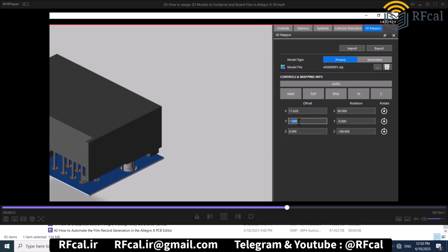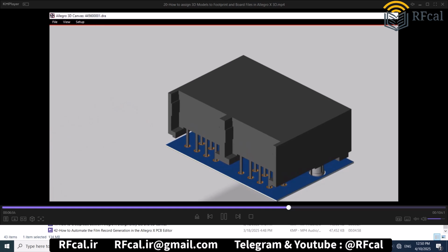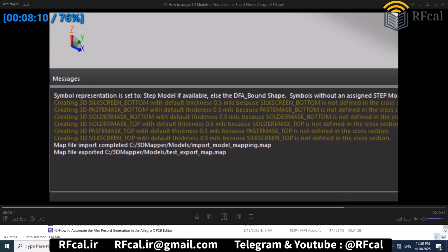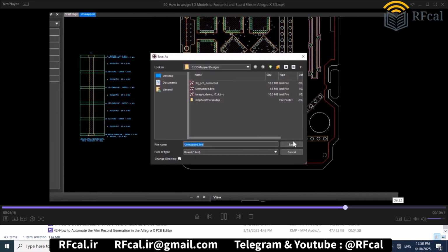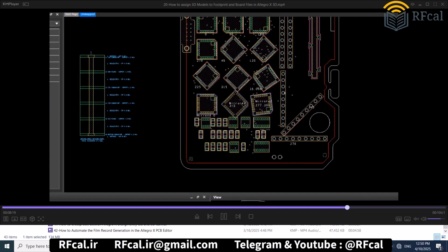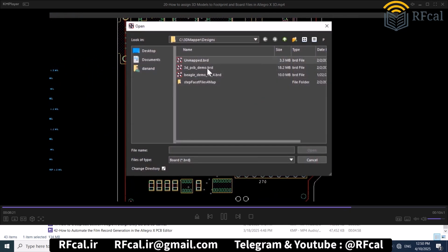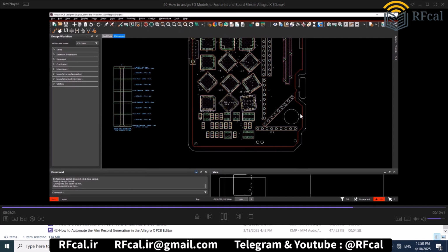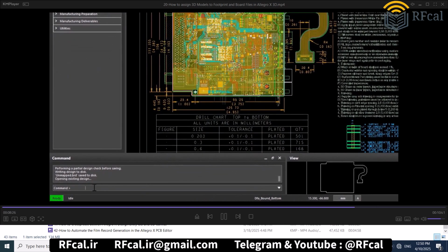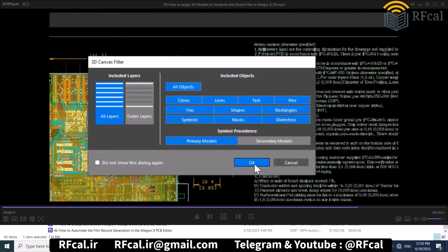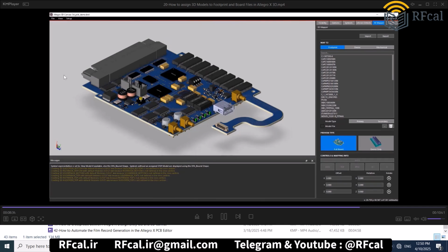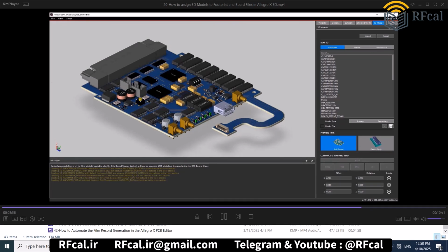position and its orientation. I am going to show you an example of importing the 3D mapper files. We have already set our library paths where the 3D model is. We will check how we will import the mechanical 3D model in the board file. Open the board file named 3D_PCB_demo.brd and open its 3D canvas. Click on the 3D mapper and bring it into focus. Select the mechanical